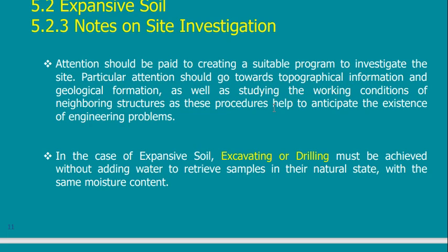Because in site investigation we use water, and this type of soil is affected by water. So if I use water in site investigation, I may eliminate the problem during the investigation, and I will take samples that have already been affected by water.